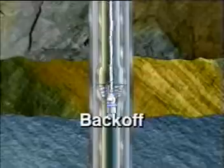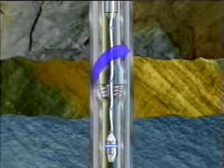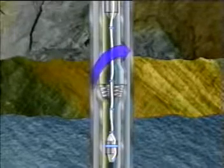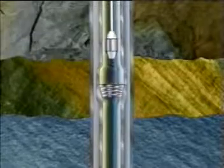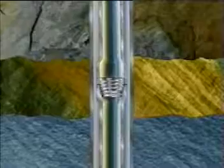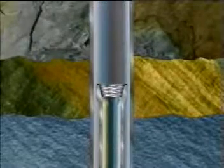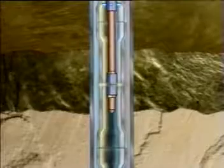A back-off is made by applying left-hand torque and holding that torque while a controlled explosive charge placed across a connection is detonated. The explosion allows the connection to be unscrewed without damaging the threads. The freed pipe is then removed from the wellbore. It is often necessary to cut a section of pipe or tubing to remove it. Among the cutting tools available to Weatherford wireline operators is the chemical cutter, which uses hydrofluoric acid to cut pipe.